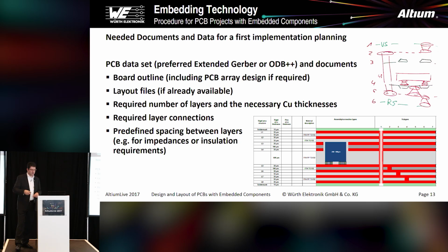So actually, this is what normally goes on. Regarding all those parts, we start with a hand sketch. We say, okay, where does something fit? Where can I have what? And so on and so on. And based on that hand sketch, we create, or every other manufacturer creates, a stack up.